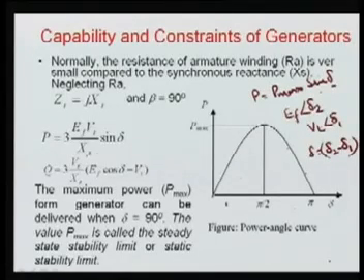So this is the voltage angle. Now again, you must be very careful: this delta is your load angle, however delta 2 and delta 1 are the voltage angles. Both are totally different. So the difference of the voltage angles is your load angle between two adjacent buses. If a system or element is connected between two buses, then the difference of their voltage angles is your load angle.